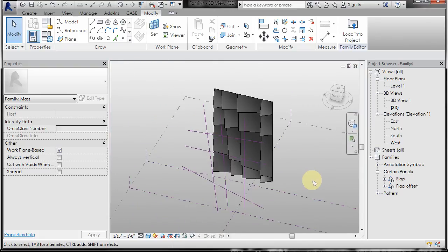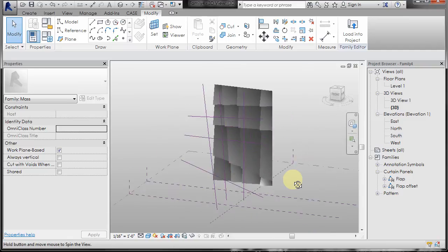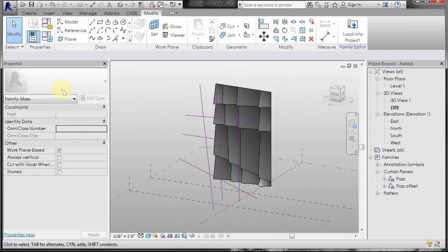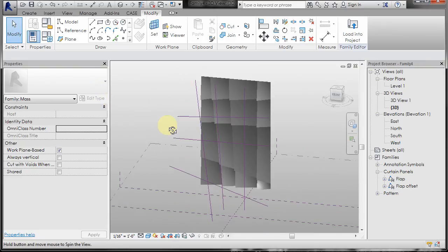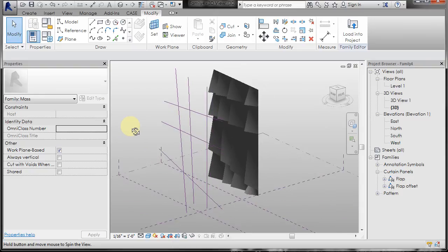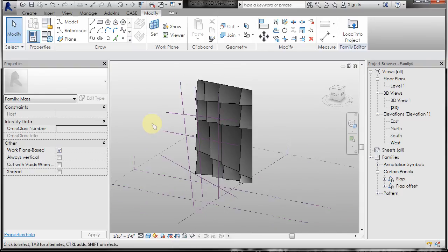So that's how you create your own pattern. This one, obviously, I used a rectangle pattern for the piece because it most closely matched that one. If you're doing triangles or something, then you want to use the pattern piece that matches where the points are. There are 4 points here, so those 4 points from the rectangle went out and found them. If you have more than 4 points, you'll have to seek out a pattern that works for you, or use an adaptive pattern, which we haven't really talked about. Okay.